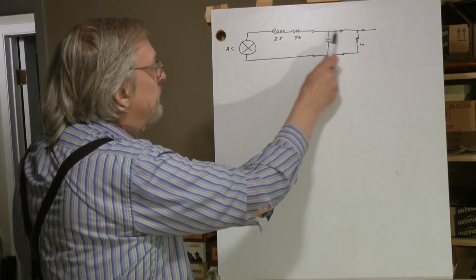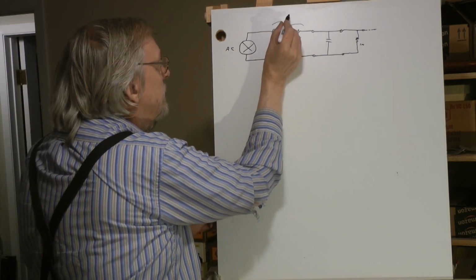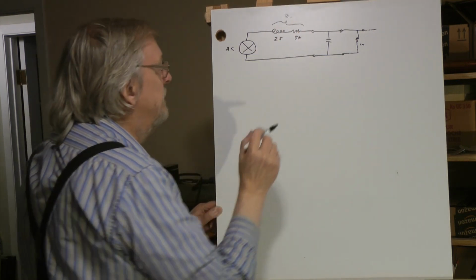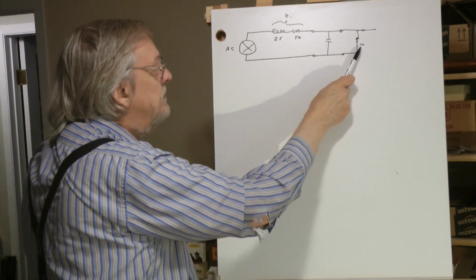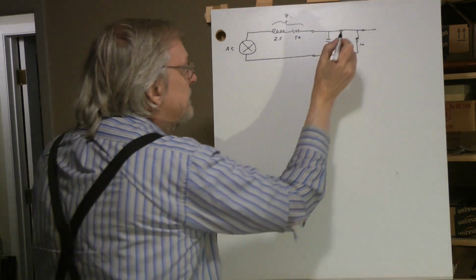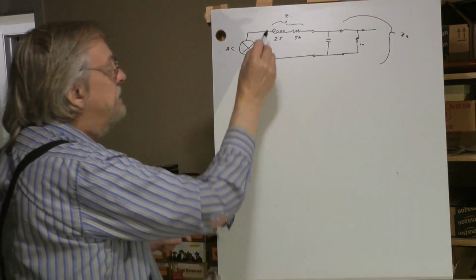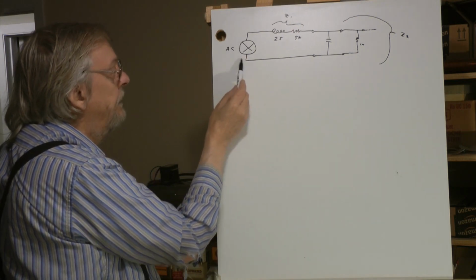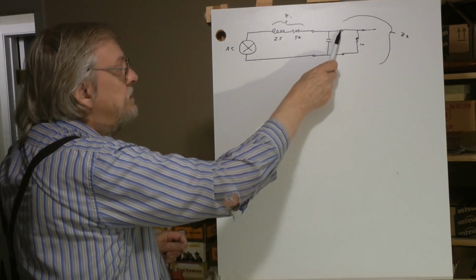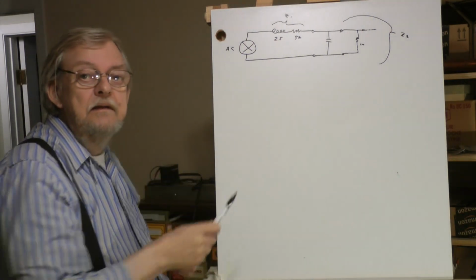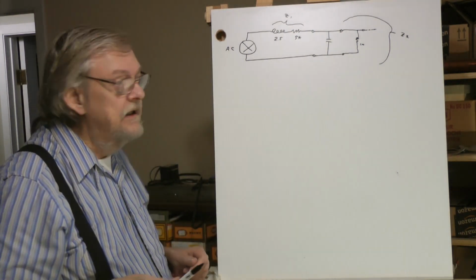This is basically a voltage divider. Current in here causes a voltage across this impedance, we'll call Z1. The current continues, now takes two paths. Because it's AC, it goes through the capacitor, and of course goes through the resistor here. So that is Z2. So the voltage divides. There's a voltage inside here. It is equal to this voltage across this impedance plus this voltage across this impedance. So this is a division. That divides the voltage: the 1 meg ohm load and whatever this turns out to be in capacitive reactance.